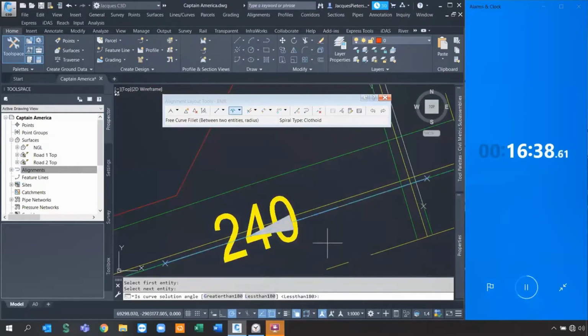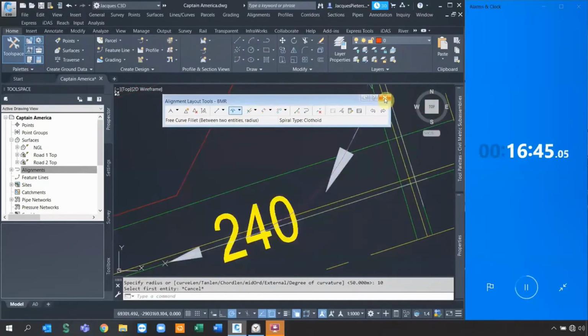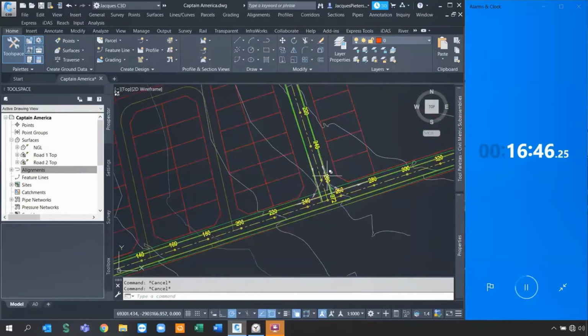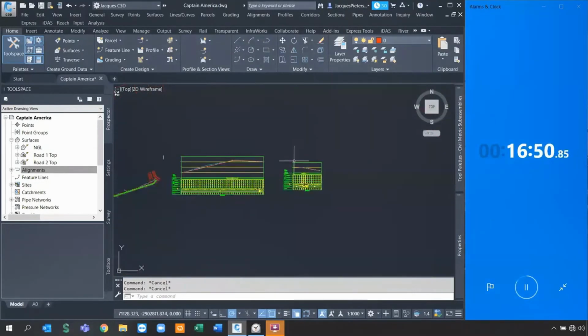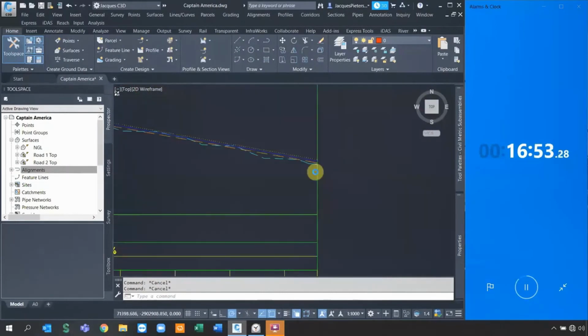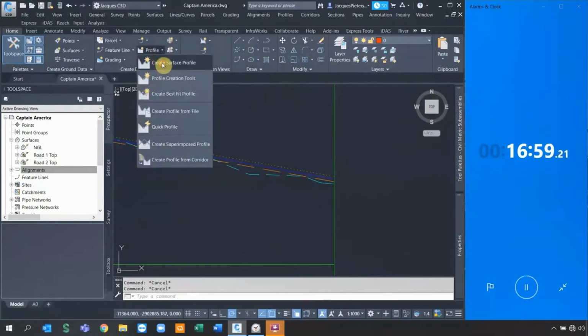So I'm going to go say alignment quickly again and specify this radius as 10 meters. So there we go. Those 2 are now nicely defined. And now the critical element is I need to link these 2 roads in profile view. So what I need to do is I need to go project road 1's top of surface so I can actually tie into that exact road.